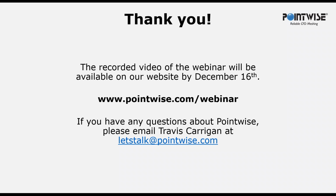All right, our next question is about cell size. Keeping the cell size so uniform all over the surface is unrealistic for a large complex geometry vehicle. How can you increase the cell size in the areas far from the boundaries to reduce the number of surface cells and maintain good grid quality? This is a multifold answer. Travis covered a good bit of this towards the end of the webinar when he started talking about area ratio and how area ratio and quality is dependent on the type of element you're growing off of. So you can take advantage of cell stretching and use that in your surface grids to save on cell count. There are just limitations to it, and the limitations are dependent on what your solver can handle.